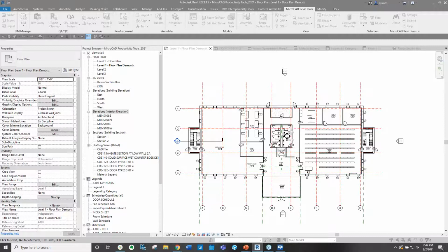But is the ability to link Revit families to Enscape assets. In Revit, Enscape assets come in as plant objects. It sounds kind of weird, but the advantage that it gives us is that we can scale those objects if they're plant objects. So typically what we'll do is if we want the asset to display correctly in our drawings, we'll use a Revit family so that they display correctly in plan, elevation, and section. And then we'll link a high quality Enscape asset so that it displays correctly in the rendered view.